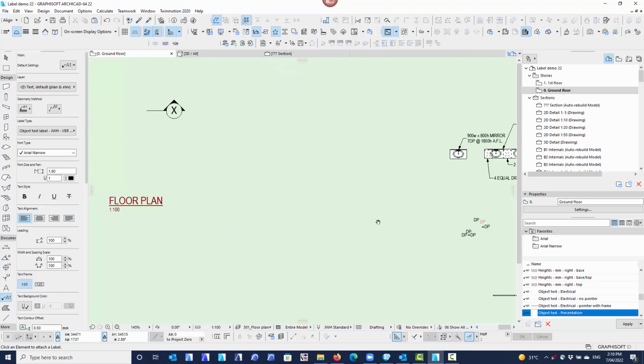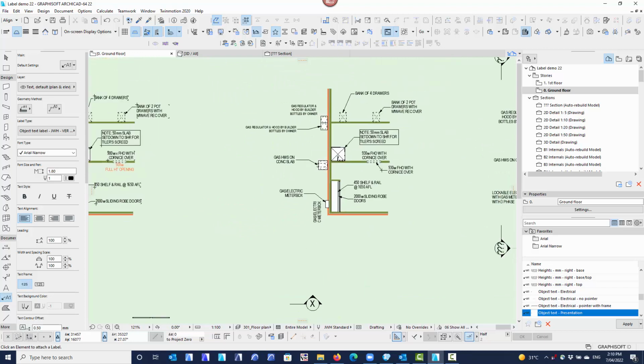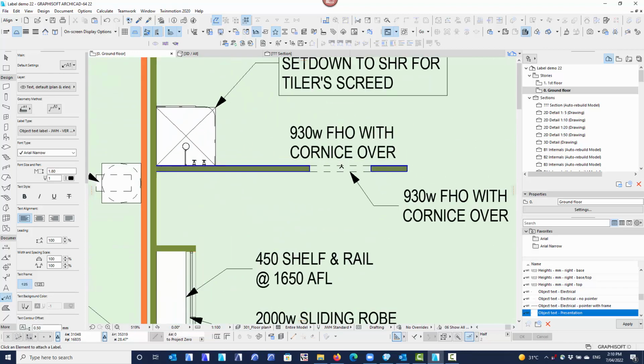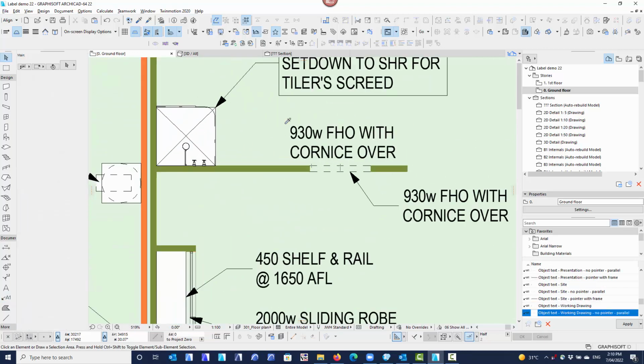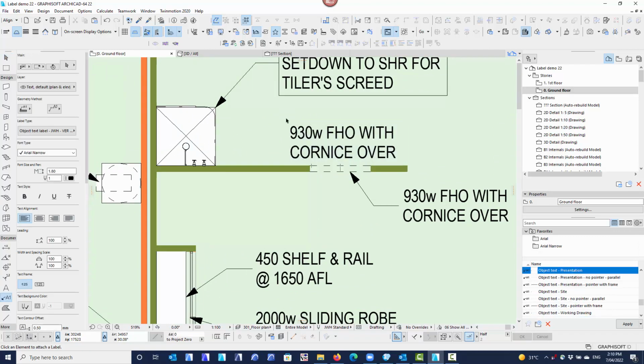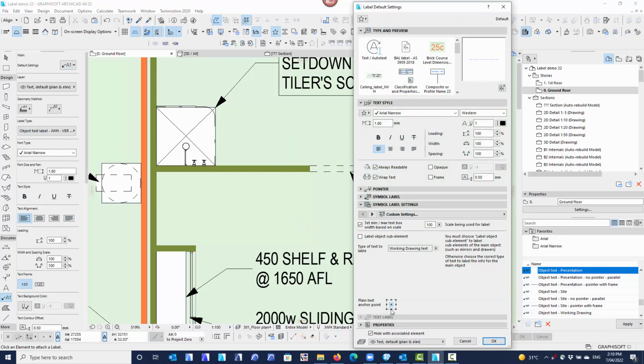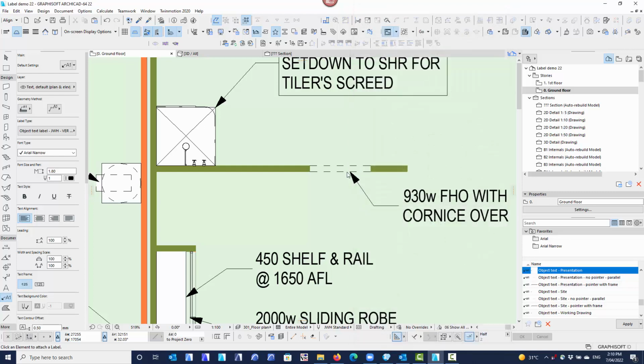And that applies also to the openings. I could apply the text here. Let me alt click that one just to get all of its properties. If I now select that and delete it, if I go into the anchor point here and say that's my anchor point at the bottom, and I click on the door, I've just got to make sure that I get the door.